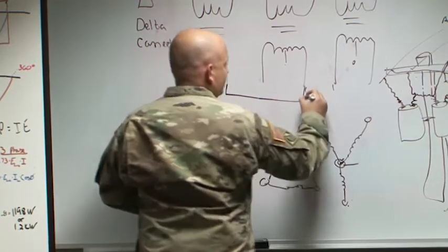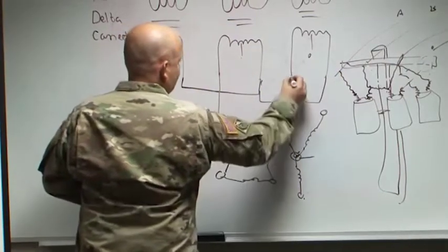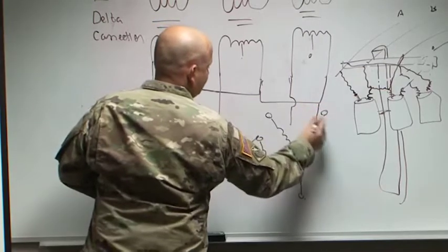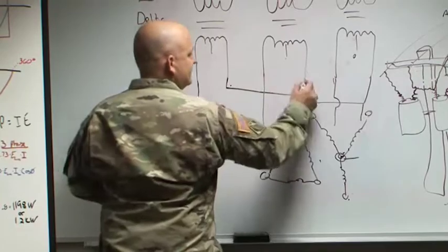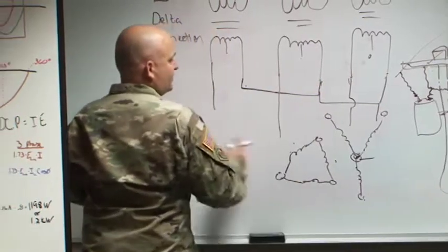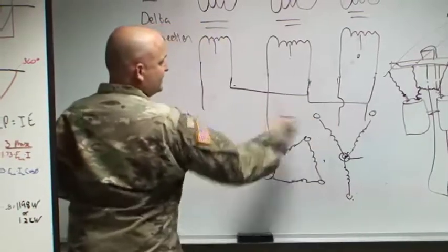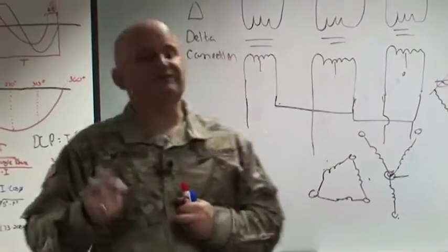Okay, I'm going to take this to this. Then I'm going to take this down and this down, right? And then I can pull this guy down too. And I'm kind of intersecting all my stuff. But because of how I interconnected these two points on the transformer, and I brought this out, say I connected to my three-phase load with this configuration, I did a Y connection, all right, because I have that same common point.